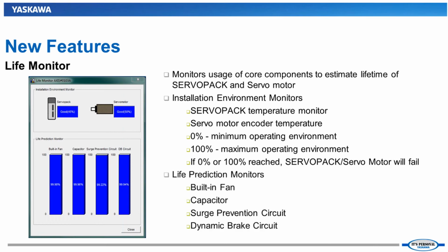And then in the bottom you have your life prediction monitor. All the components that typically lead to a servo pack failing will be monitored for their usage over time. As you can see with this one, everything's still pretty new, at 99% of their life cycle.